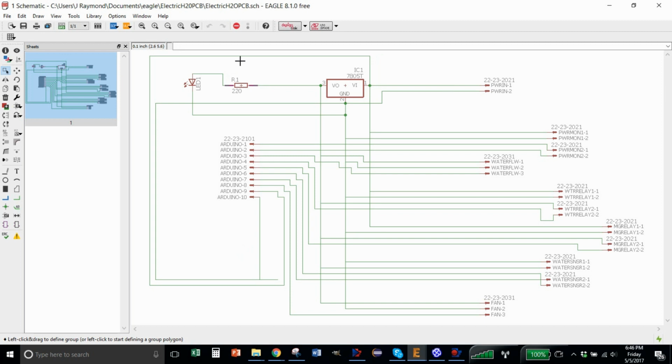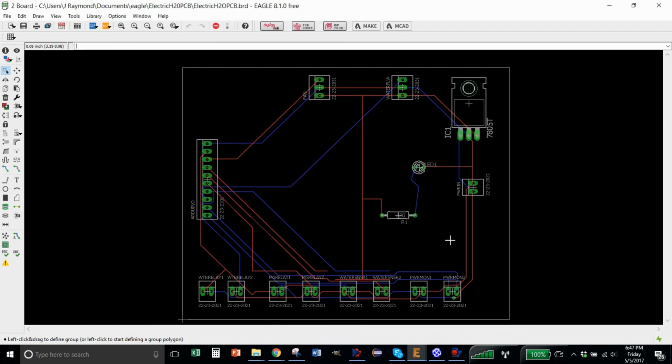But what we're looking at right now is actually converting that SysML model that I showed you, which had all those lines going all over the place, into an actual electrical schematic. And we're showing all the different connectors that are on here: the computer, an LED, a resistor, a voltage regulator. So quite a few different things on here. And you connect all those things up. And then what you do is you hit the layout button, and it'll actually lay everything out for you on a board, which is what I've done here.